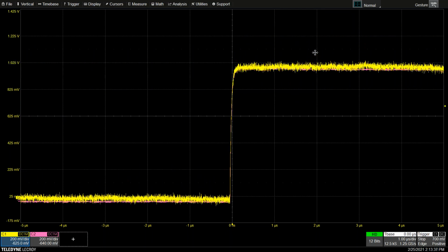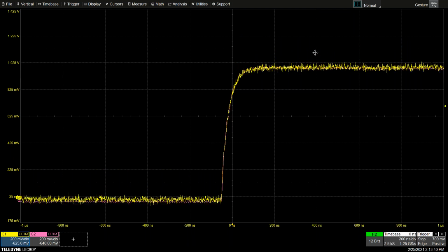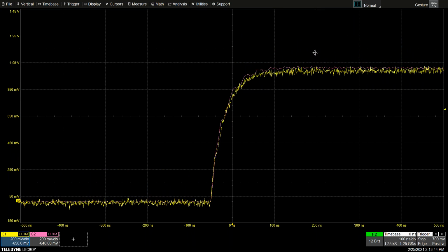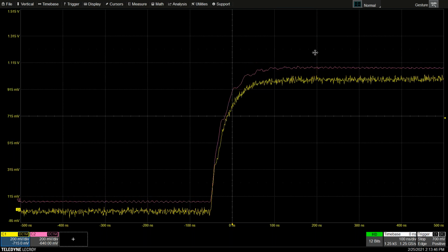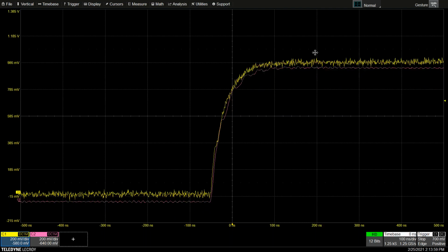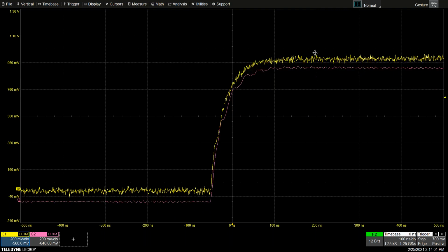And I also want to point out, I'm zooming in for a reason, right? I also wanted to show you, look at the timing measurements, right? We are also seeing that channel 2, when I reacquired, has a little noise on it from my environment here. But at any rate, look at the rise time measurements of the yellow waveform. And we can see, geez, rise time measurements will be affected by that, or fall time.